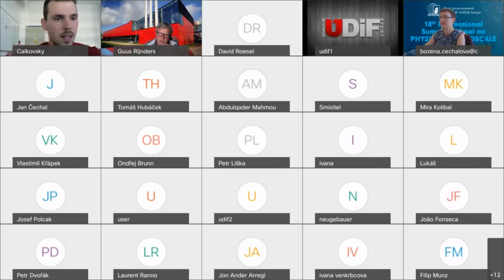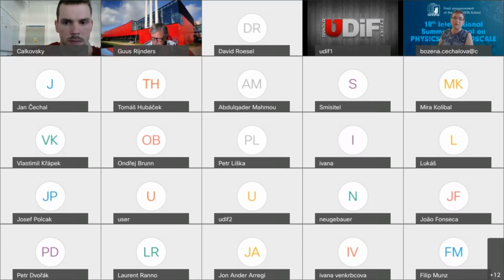Yeah, it's a good question indeed. Be aware that in our case, the PZT is underneath the mirror. So we hope that most of the intensity is already being deflected from the mirror. The temperature is an issue indeed, because in some applications you use elevated temperatures, and of course you also have the illumination from this highly intense EUV source. But PZT can withstand quite high temperatures. For instance, for printing, like Canon and this other company do, it is typically done above 100 degrees C or so, and that can work quite well. You have to work on the composition a bit and on the crystalline quality, but then it can really work at elevated temperatures.